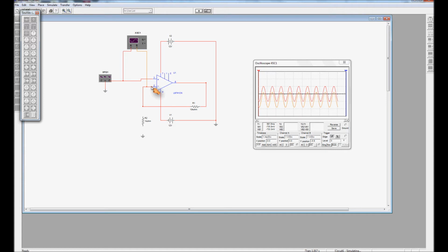The other reason though is that were any current to flow into the inverting input, a voltage drop would be formed across the op-amp itself, and therefore the signal in could not equal the signal out. In the ideal operational amplifier, no current flows into the inverting input. When I ground R2 and redo the sim, we can see that the signal voltage across R2 remains unchanged.